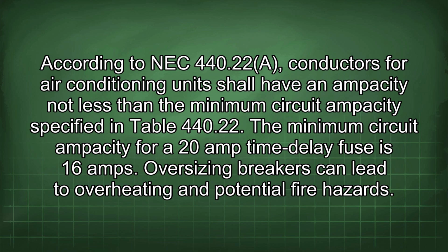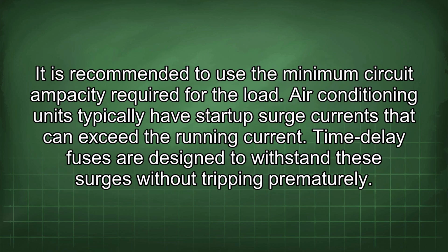Oversizing breakers can lead to overheating and potential fire hazards. It is recommended to use the minimum circuit ampacity required for the load. Air conditioning units typically have startup surge currents that can exceed the running current. Time delay fuses are designed to withstand these surges without tripping prematurely.